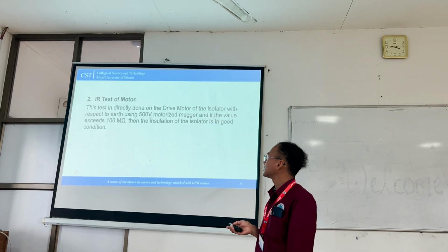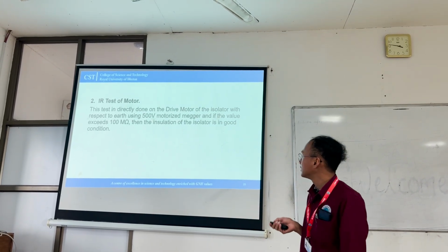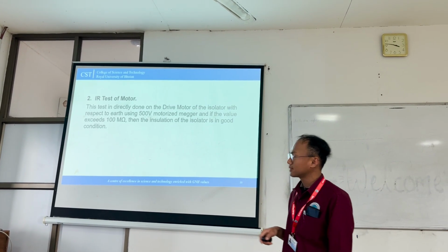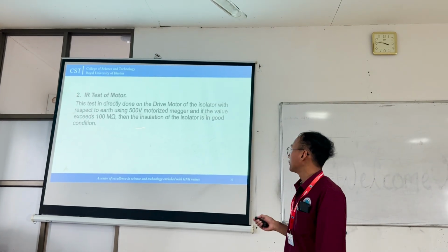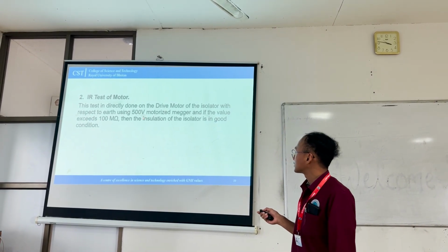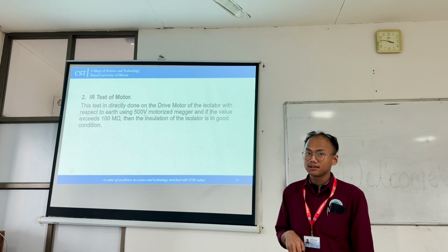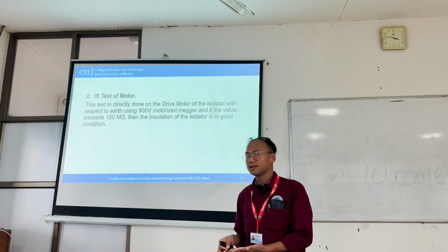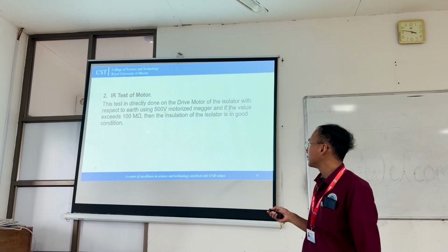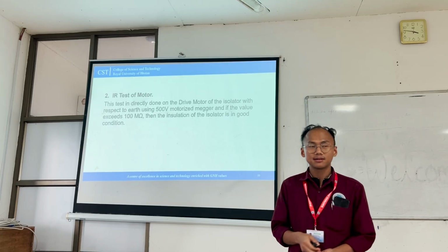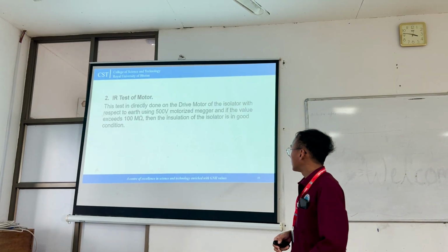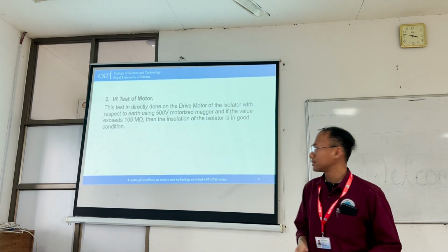Likewise, secondly, we have the IR test of the motor. This test is also done using a megger, but we use a 500 volt motorized megger, and the expected value should be greater than 100 megaohms to prove the quality of the insulation.